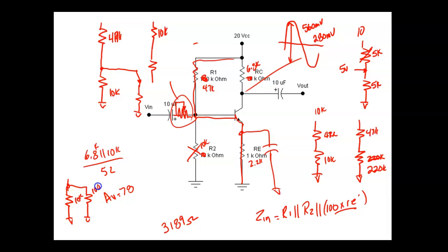What's my total resistance? A 10K in parallel with 100K. You got 90, yeah. So since this resistor in the emitter is seen times beta, when that R2 is in there, we just ignore it because it's not noticeable. We calculated 1.7 volts and we measured 1.7 volts because that is being seen as a 220K over there. So what's a 220K in parallel with a 10K?